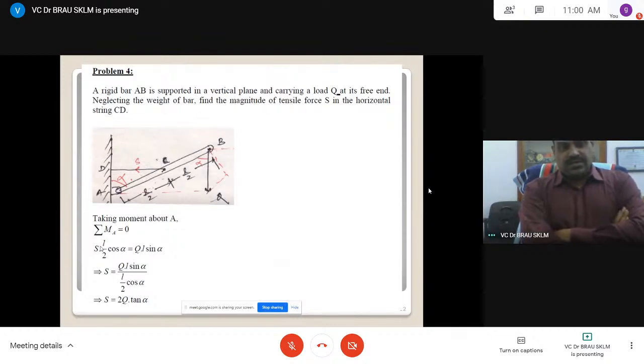The meaning is, if you take moment of the component forces about any point, it equals the moment of the resultant force about the same point. In other words, clockwise and counterclockwise moments combined and equated to 0. It is a pure rotation, having 1 degree of freedom, so you can determine the 1 unknown.